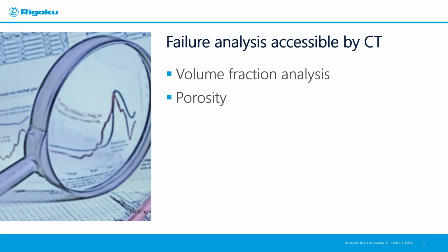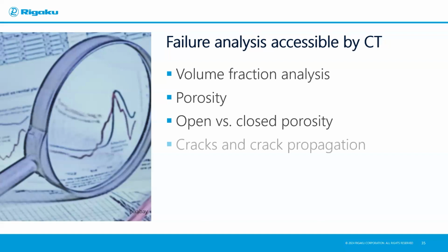And of course, its location, whether it's open or closed porosity, will impact the stresses that you have. And of course, these small pores can propagate into cracks that eventually cause structural failure.